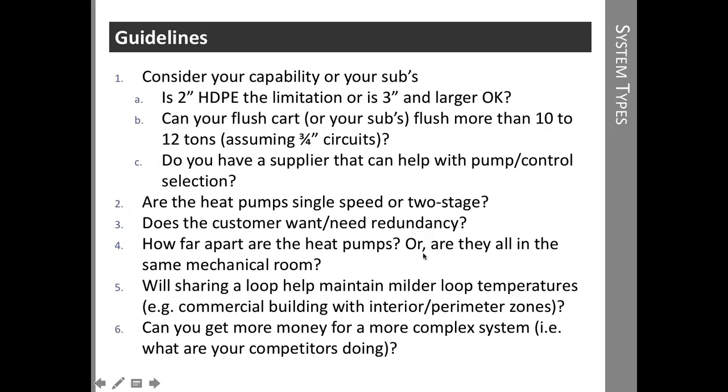How far apart are the heat pumps? If we have 1 heat pump at one end of the building and 2 at the other end, it probably doesn't make sense to combine those 3 on a single loop, just because of the amount of piping. But if they're all in the same mechanical room, that's a little bit easier to justify a common loop. And that leads into number 5.